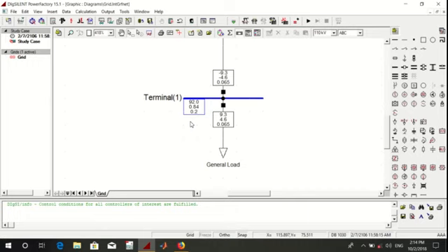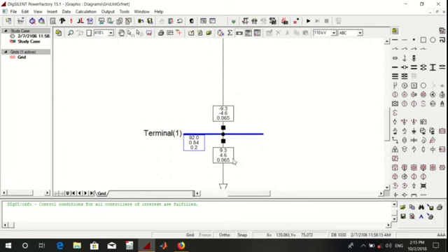Now what actually happens in practice when the load flows and the load is connected, our system is on? The next bus bar terminal voltage is 92 kV instead of 110 kV, and it becomes 0.84 per unit according to our base, at an angle of 0.2 degrees. This is our load defined, that we have defined as 9.3 something and 4.6 something active and reactive power. How much current flows is given here, that is 0.065 kiloampere flowing to this load.